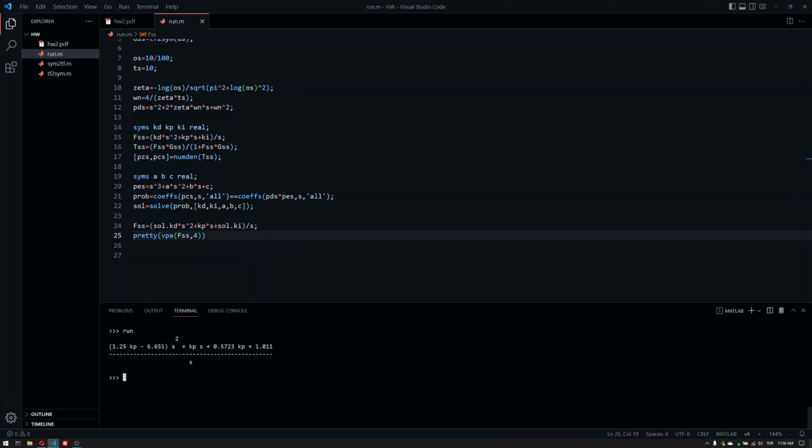So these are all the PID controllers that have the complex conjugate pole, calculated by zeta and omega n, as a common complex conjugate pair of roots. So basically we have assigned the poles, but we don't know what the residue poles look like, so they will be moving, but all that is going to happen is we will have 2 poles at the exact same spot, but the other ones will move. So basically, this is a family of all PID controllers.